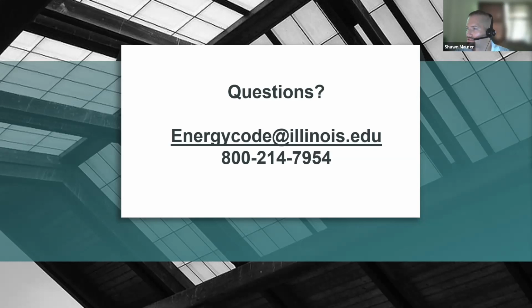We also had a question about when entering the fenestration type and amount, what dimensions do you use? You would use the rough opening for fenestration inputs. The reason being the NFRC rating for that window includes the window frame and things like that in the U-factor, solar heat gain coefficient analysis of the window. So you would be entering the rough opening size.